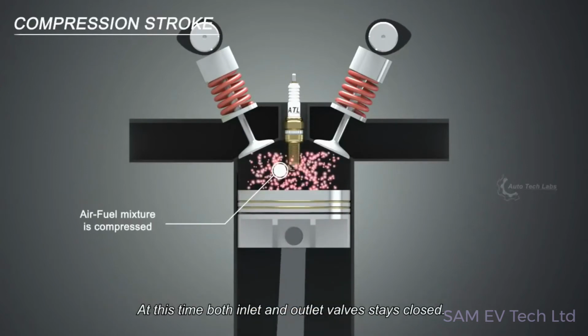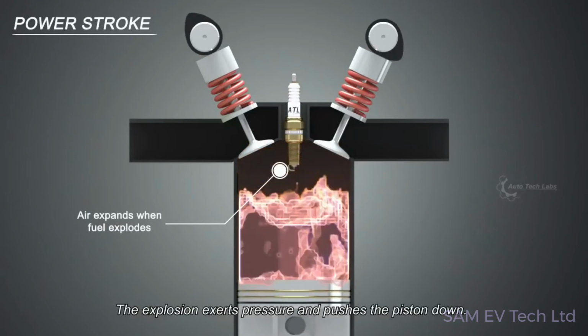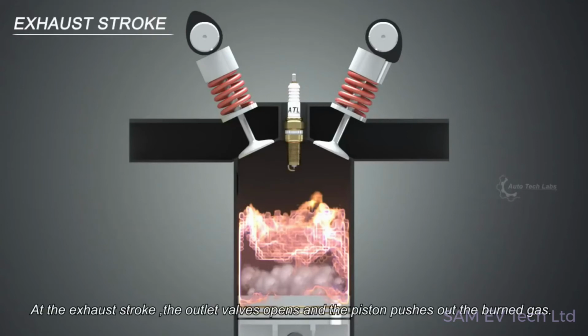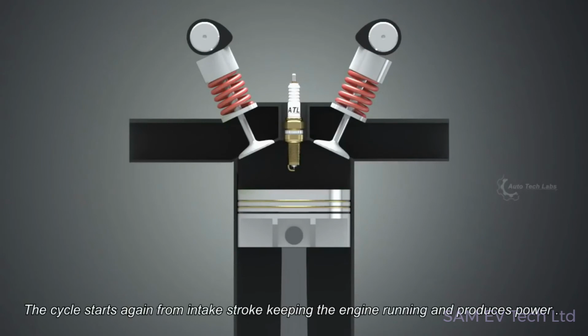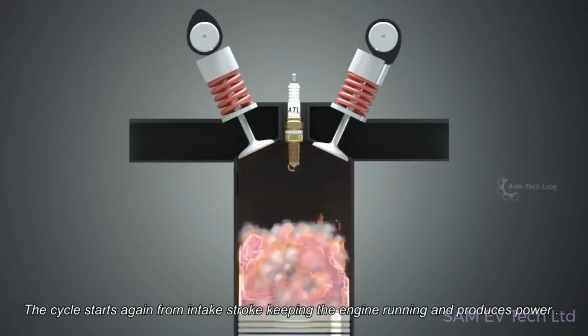At this time both inlet and outlet valves stay closed. At the end of compression stroke, the air-fuel mixture is ignited by the spark plug. The explosion exerts pressure and pushes the piston down. This is the power stroke which produces power to the crank. At the exhaust stroke, the outlet valve opens and the piston pushes out the burned gas. The cycle starts again from intake stroke, keeping the engine running and producing power.